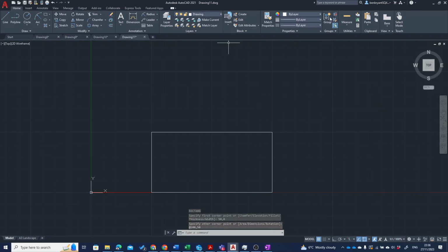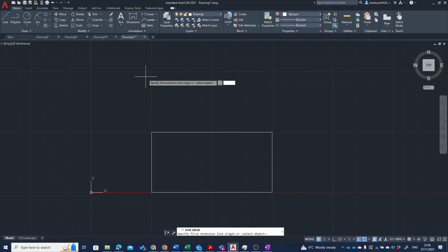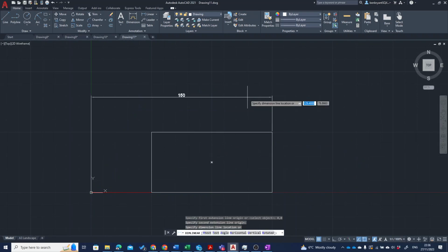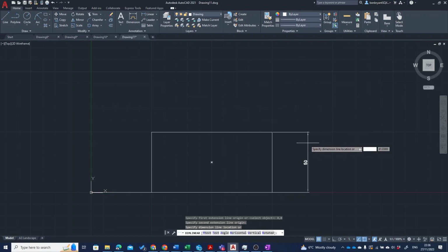Now, just to double check, if I go a linear command, if I go from 0, 0, this should be 150. Which it is. So just to double check that that was an incremental change. So that's 150. If I move it the other way, it's 50. Like exactly what my code says. So I've done a quick check to verify that's exactly what I need.